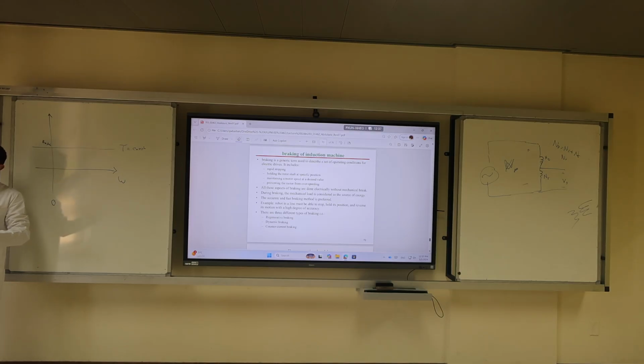The speed has to be constant. Let's say this is the elevator design speed. It would accelerate until it reaches the design speed, and then it will maintain its speed constant. And throughout the whole process, the torque has to be 150. So how do you do that? What does the curve look like? In physics 101, when you push a box from the start, you push it at the same torque, and then you stop.